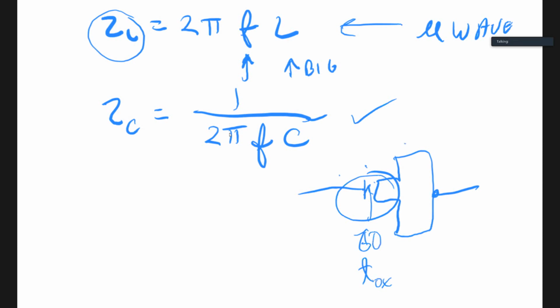So we want to get rid of the inductor. And what we're going to do next is to look at a clever simulation of an inductor that uses only op-amps and capacitors. And to the driver and as a load, it looks just like an inductor. So that's very convenient.